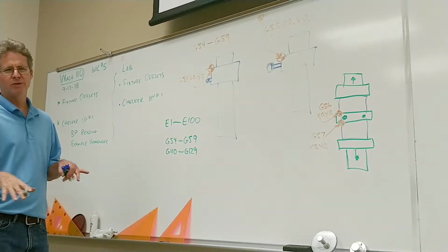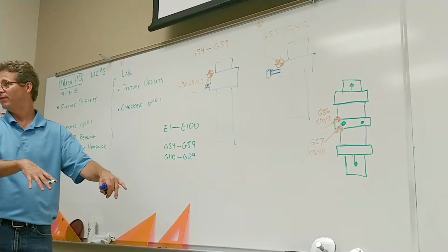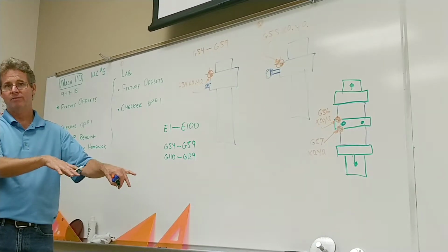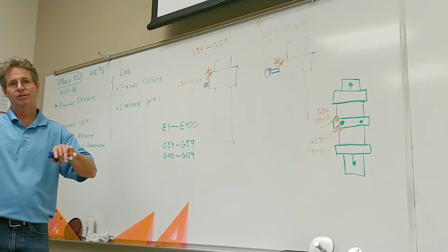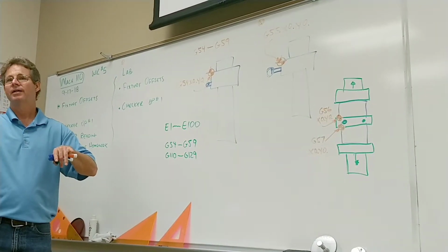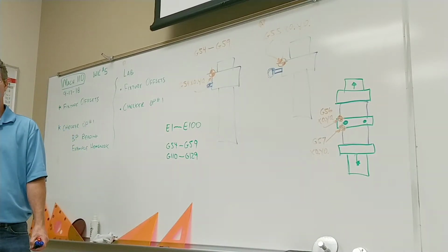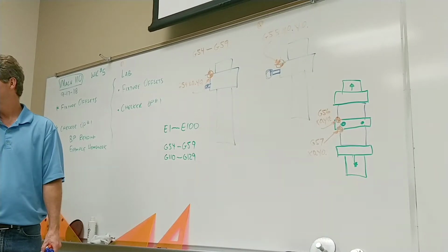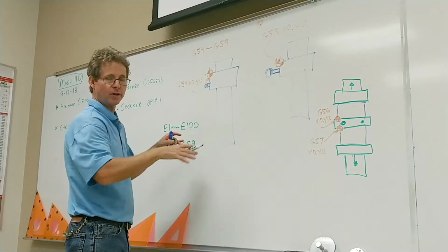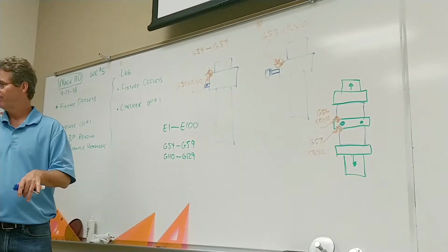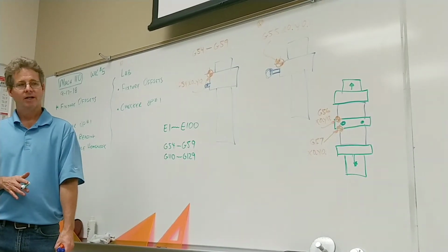Some people, you should move your vises around periodically, but some people like to put their vises there and never move them. Never. And they put everything in there on Mastercam and SurfCAM. They set one G54 and everything is on the CAM system. And they just always program with that. That's fine. That has pluses and minuses. It has some pluses in that you could get things going very quickly in your machine. It's got some minuses in that you're always machining on certain parts of the ball screw. You're wearing out the machine in just a certain area. Maybe if you did that and you moved the vises every 3 months or so, that might be a good idea.